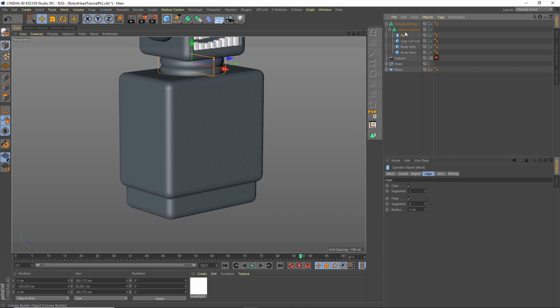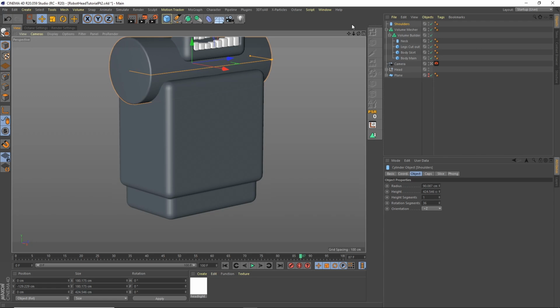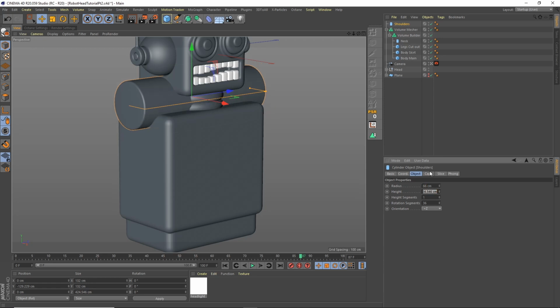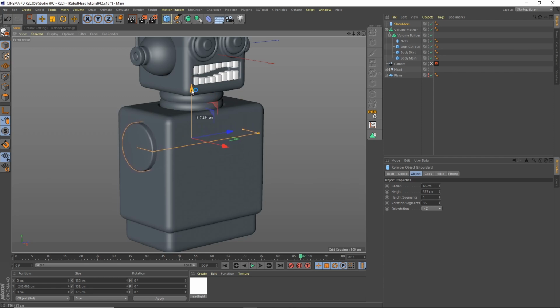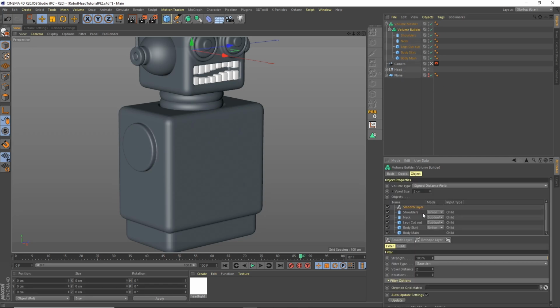and then we'll duplicate that, and we're going to call this shoulders, and we'll change the orientation to plus Z. Let's change the length. Let's make this about, say, 66, 375. Now we know it's centered, and we just want to have this roughly at the top. Okay, so a little way just underneath the end of this curve. Let's add this in, and we can leave that as is. We'll add a smoothing on that, which will bring everything together a bit. I'll just set this to 1.